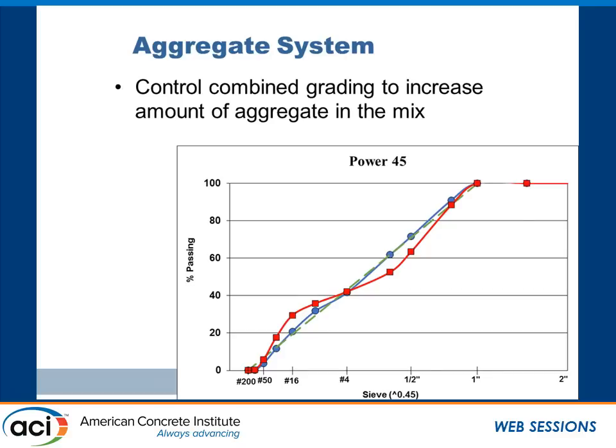And the other one is that the Air Force or the airfield guys, there's a consultant out there who says no, he likes it to drop off below the curve, round about the number 16 sieve, because in his observation, and this is purely empirical, if you get it to deviate from the Power 45 a little bit, then sliver spalling goes away on airfields. And all the airfield people jump up and down and say, yes, no more FOD, this is a good thing. But he couldn't tell me why, and he couldn't be too explicit about how much. But we want to be off the curve just a bit to provide some space for the paste to get into.